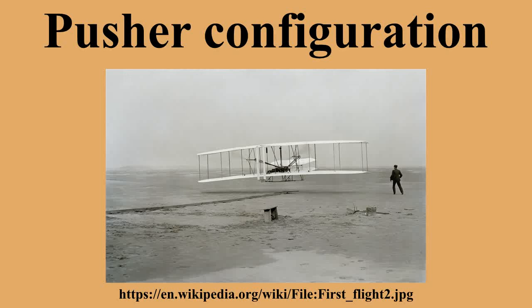Efficiency can be gained by mounting a propeller behind the fuselage, because it re-energizes the boundary layer developed on the body and reduces the form drag by keeping the flow attached to the fuselage. However, it is usually a minor gain compared to the airframe's detrimental effect on propeller efficiency. Wing profile drag may be reduced due to the absence of prop wash over any section of the wing.